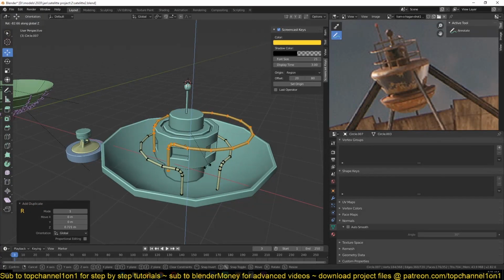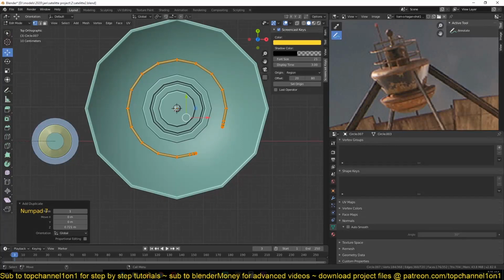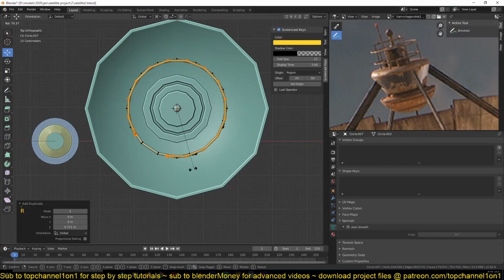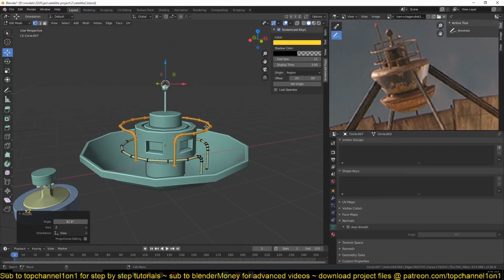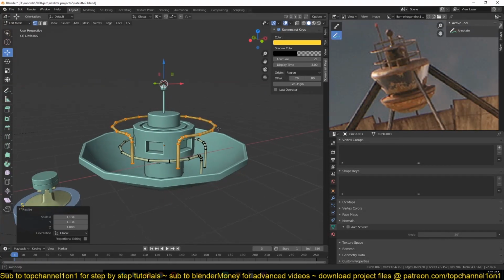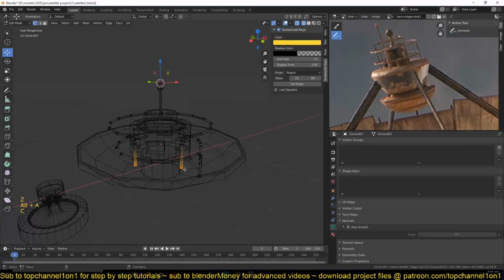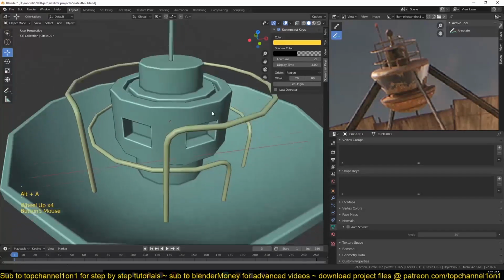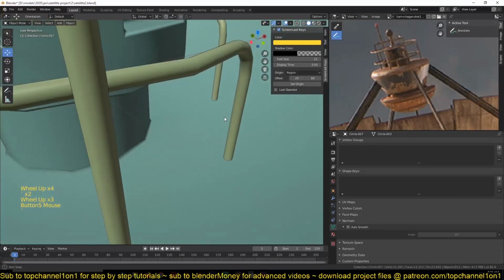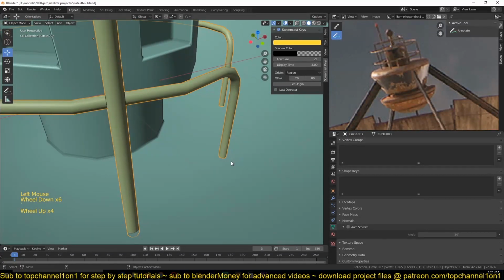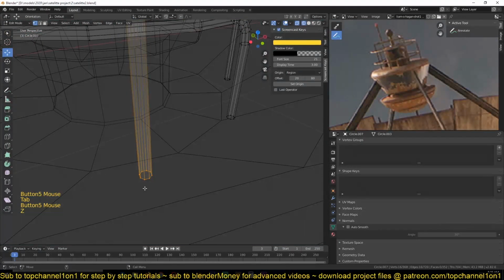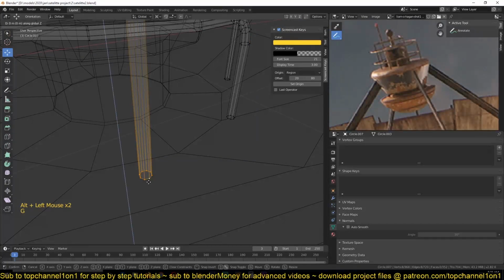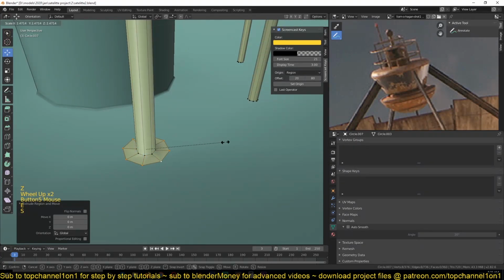Now we can rotate this. Make sure that we are rotating it using the cursor as the pivot point, so that it's rotating in the center. Maybe we can scale this up a bit. And now select these points here, push them all the way like that. But they're just cutting through the mesh, and it's not really giving us the look I want. So what I can do is go in here, maybe change the pivot into median, sorry, extrude, push that down to have something like that.